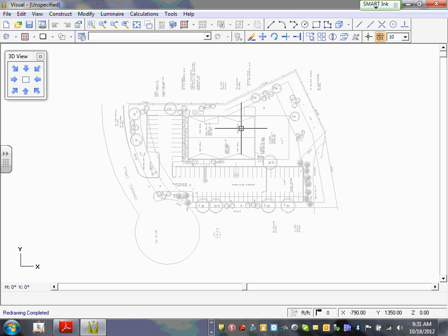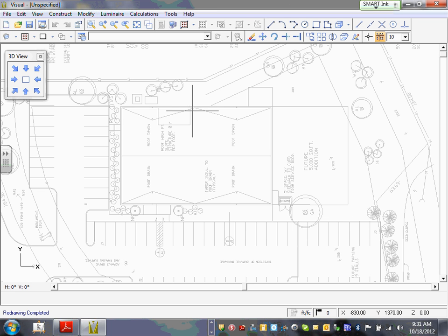Next step, guys: I'm going to build, see that building here? I'm going to put a box around the building. First, I don't know if you guys can see the default here. Put your snap at 0.1 so you can snap closer. Put your ortho right here, snap 0.1 ortho, and I'm going to make a box around the perimeter of the building. That's what I'm going to do.